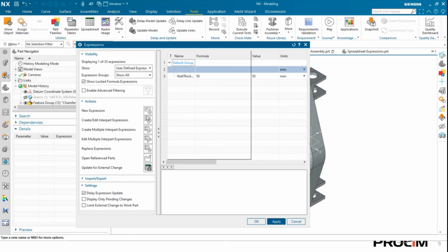What is a user-defined expression? Well, I mentioned that if you were to do any master variables, such as, for example, this is one that I just created in NX. And if I were to just say user exp and hit enter, not just because I'm doing it in my user-defined expressions, but just because let's say 600 over here. And if I hit apply, it creates a user-defined expression. Now, I just created this, but I haven't linked it to anything.